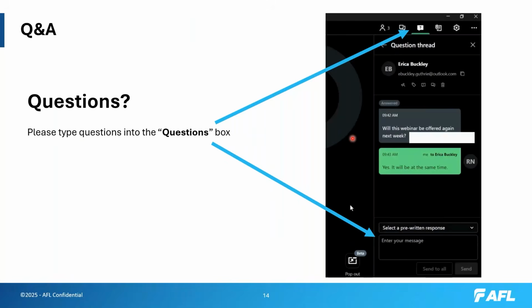With mass fusion splicing in particular, I used to do a lot of field maintenance and troubleshooting, and within 5 minutes of arriving on site, I would ask the technician, hey man, can I get my hands on a Q-tip? If he couldn't give me a Q-tip in less than 15 seconds, we were going to be working on hygiene in some form. Q-tips, a high reagent grade alcohol or good quality cleaning fluid is a must. I would concentrate on any of those elements that contact the cladding of the fiber after it's been stripped. So you clean that fiber, you get it squeaky clean.